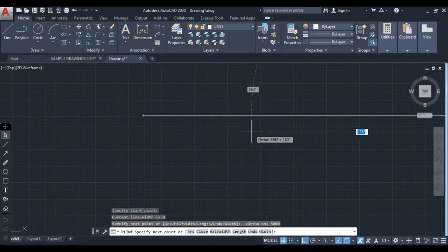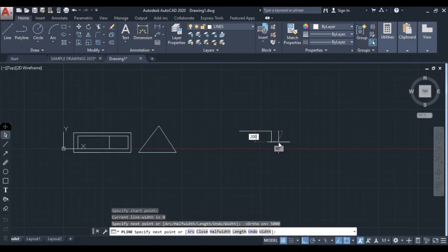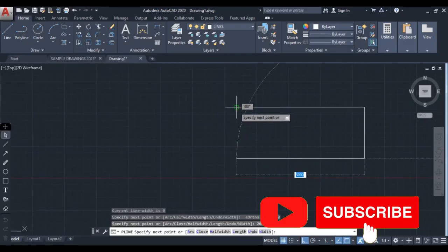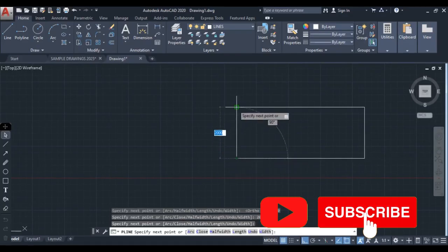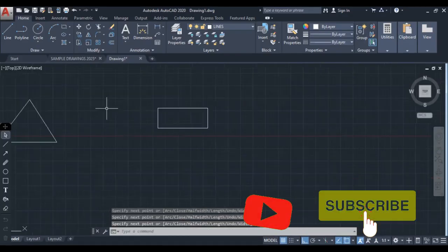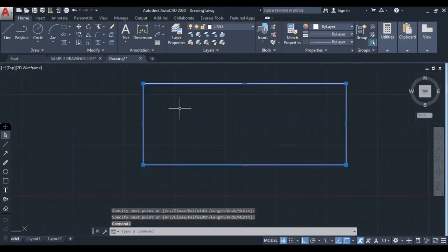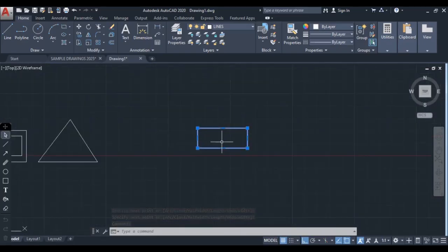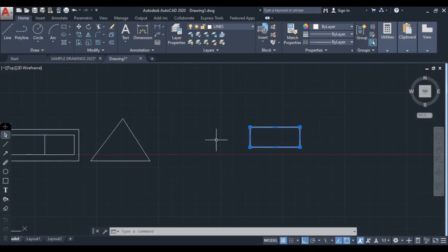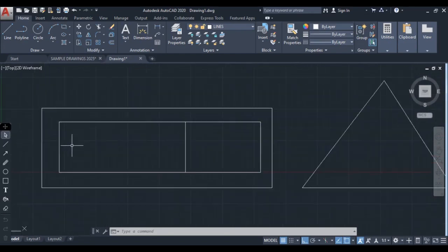I bring it down to 2 meters. I hit the enter button. Take it back, and I use my snap and track mode to click. You can see now I want to select this. If I select it, I'm selecting one line. That is the use of the polyline tool. The polyline tool, sorry. But the line tool separates everything you are doing to be single.